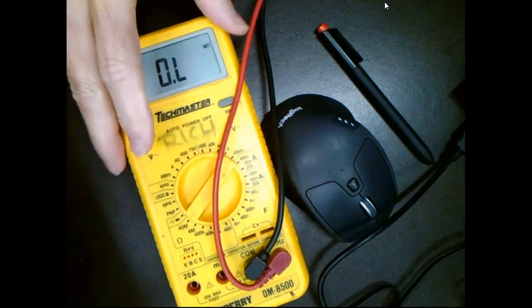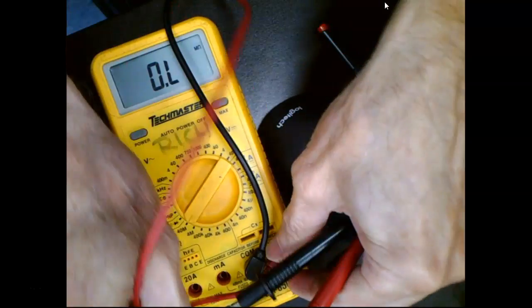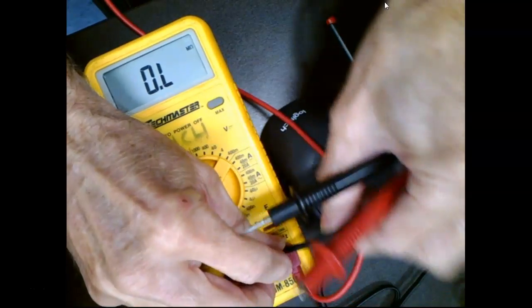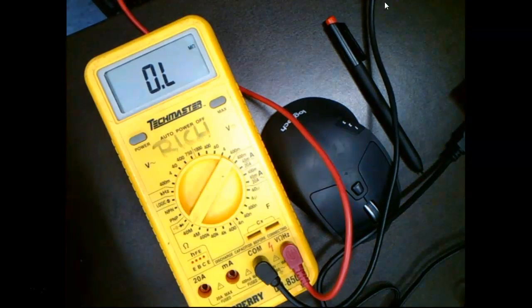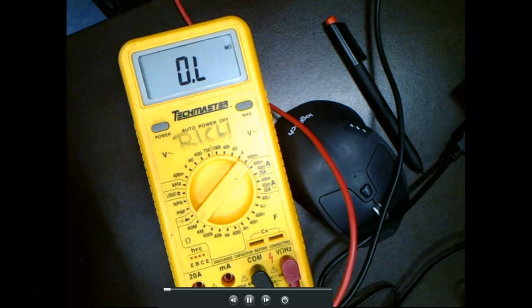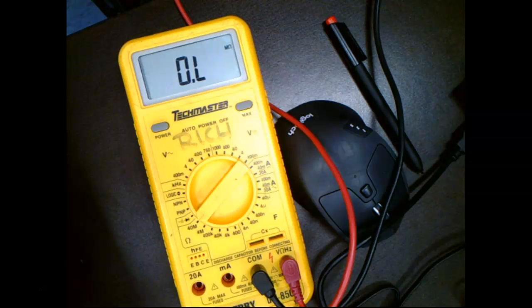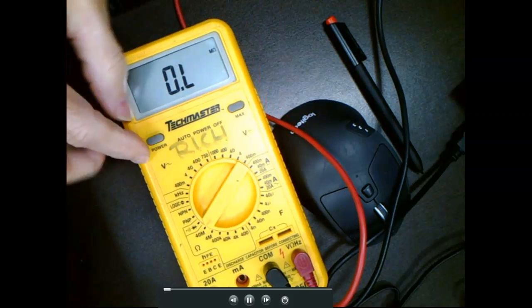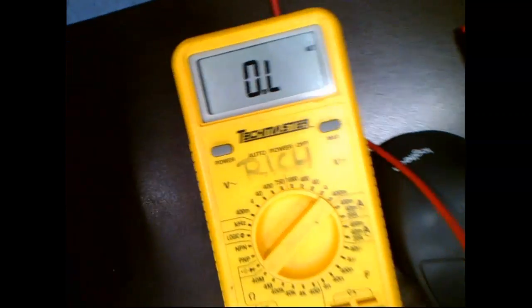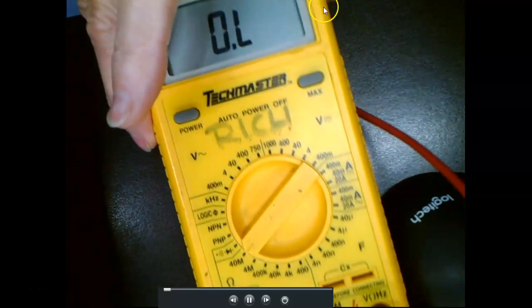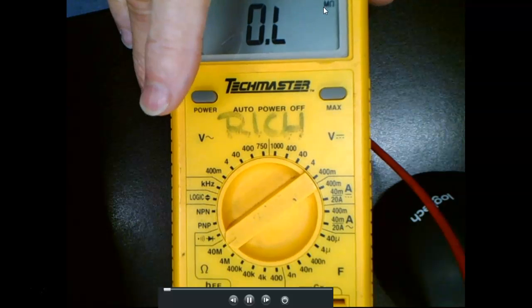I prefer meters that have the scale on them because I don't have to think about what the meter's telling me. We have this happen all the time in DC. The meter will come up and say 0.3 k ohms, and they'll write 0.3 k ohms, instead of writing 300 ohms, because the meter doesn't scale right. I like these because you decide what scale you've got. So now overload means something, right? You understand that?